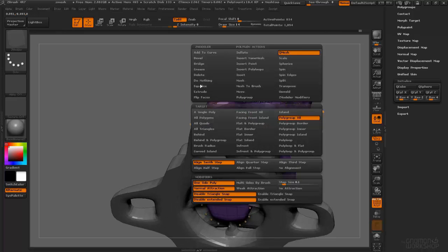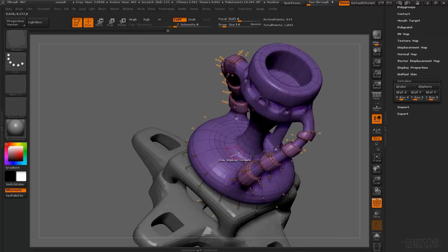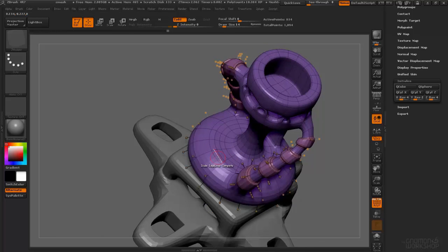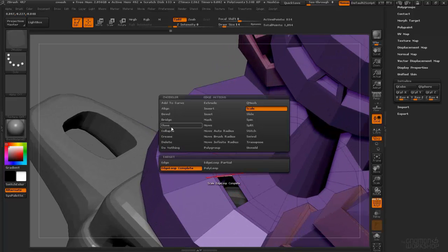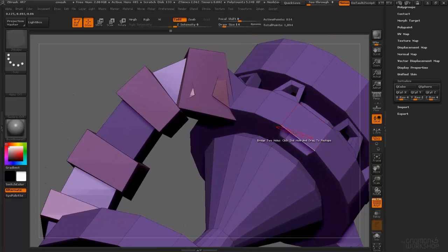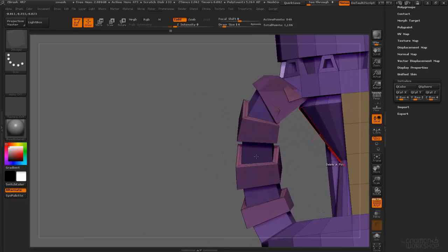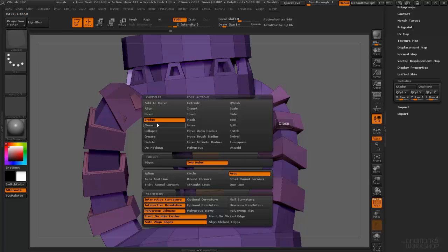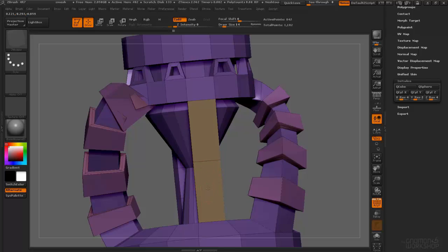So we'll go ahead and delete this face here and do another bridging from here to here. Go ahead and select edges, bridge, edge 1, and select edge 2. There we go. Now we've got our connectivity between both. And of course we can go in and get rid of any sort of edge loops that we don't need. Just click delete, edge loop complete, and we can delete that edge loop, and then just scale this edge loop down.